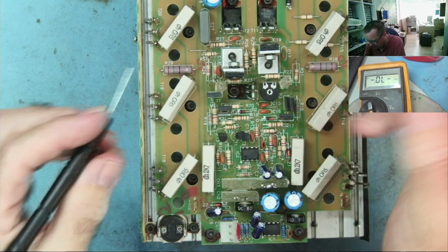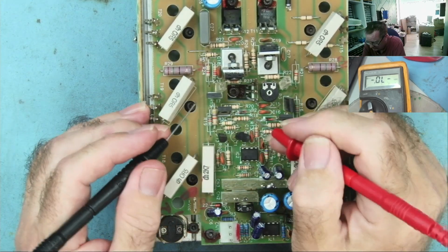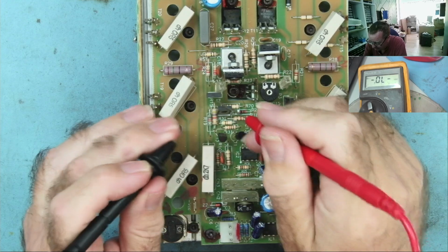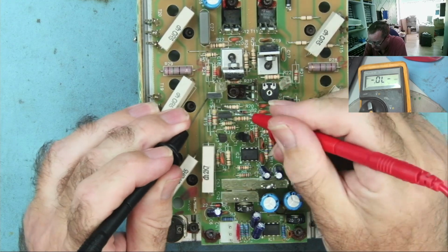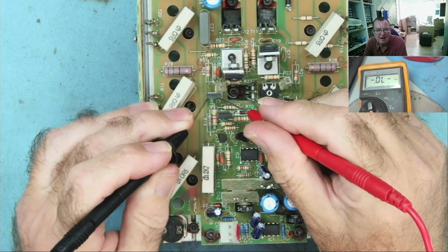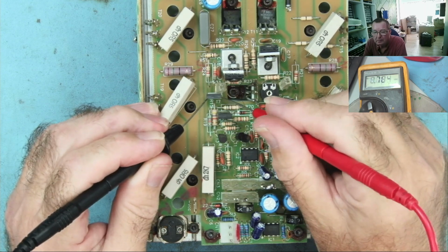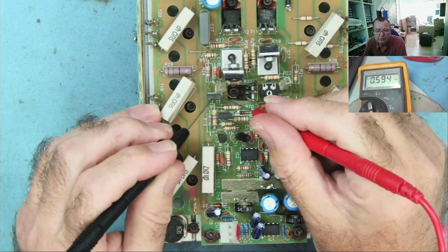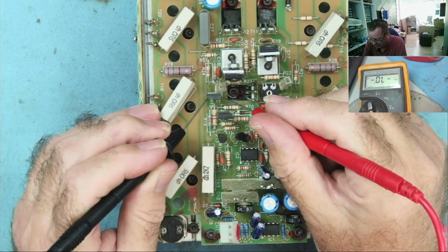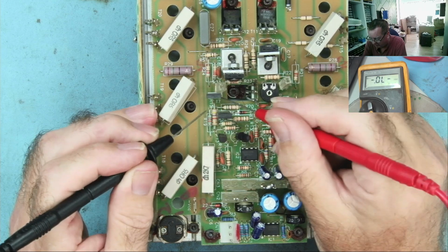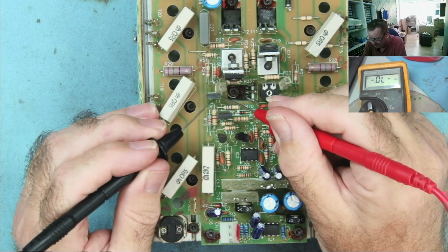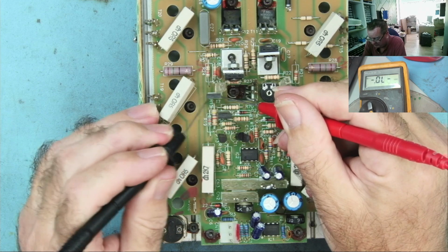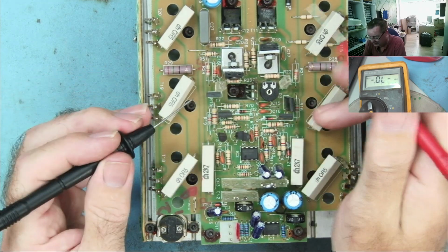While we have the circuit board here, let's have a quick look at it. So there are some more transistors. Let's see if we can identify them. So this one first, I don't know what it is, but that's reading fairly high. Okay. That reads like a diode junction. That reads like a diode junction. 0.594, 0.606. So NPN, because the positive lead is on the base, NPN, okay. Collector, emitter, good transistor.